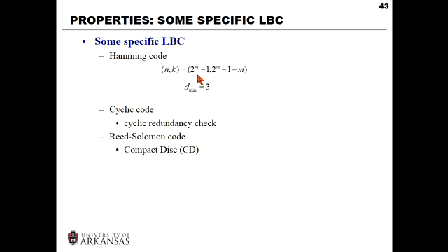That's why it's called Hamming code. n is 2^m minus 1, and k is 2^m minus 1 minus m. Once n and k follow this relationship, there is also a guideline about how to design the G and the H. So given an m, we can have different (n, k) pairs, and we can design codes of different length.